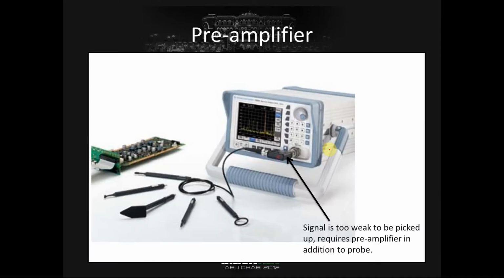When you use the probe, you'll see there's a pre-amplifier on this. So you need that preamplifier if you're using a regular scope. If you're using the OpenADC, you may not. You may still need one. I'm not going to guarantee the gain is going to be high enough on just the board.